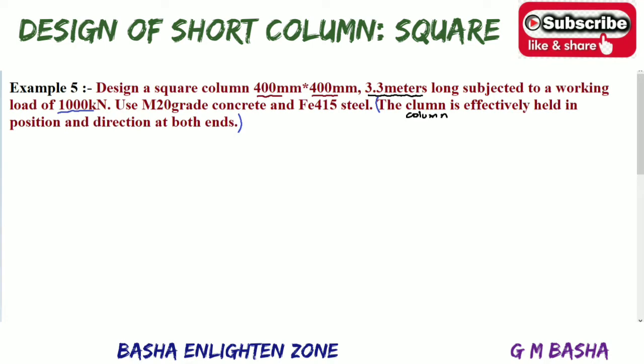In this lecture, I would like to explain another example, that is example 5. See here, design a square column 400 mm by 400 mm, 3.3 meters long, subjected to a working load of 1000 kilonewton. Use M20 grade concrete and Fe415 steel. And they also mentioned one condition, that is the column is effectively held in position and direction at both ends. So first you observe the difference between the previous problem we solved and this problem.